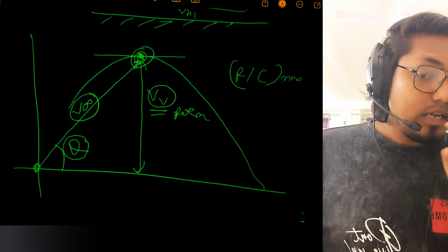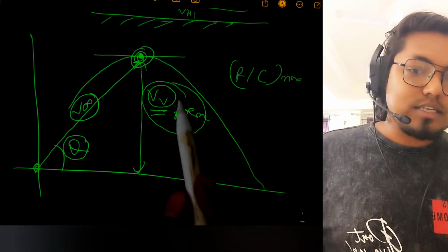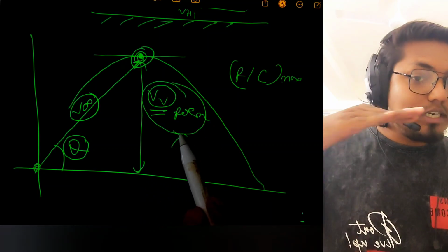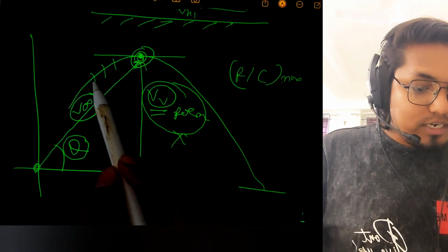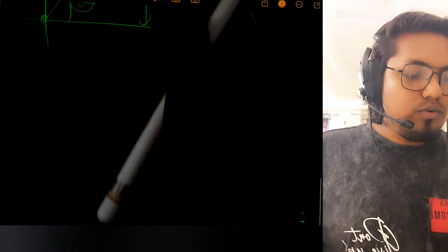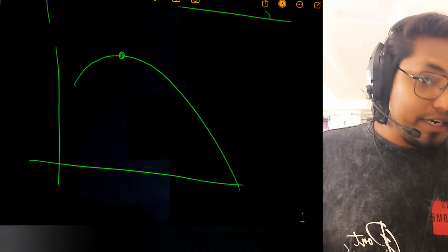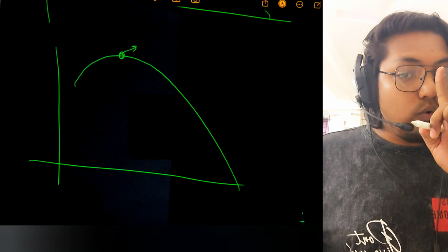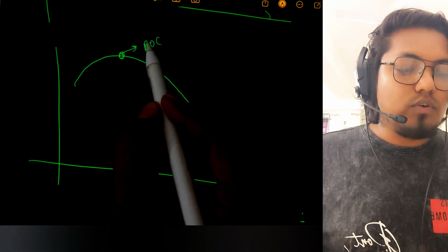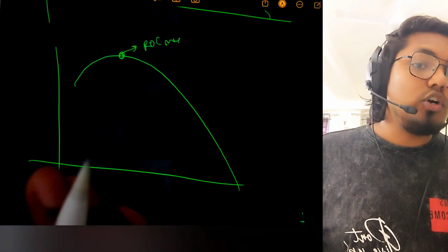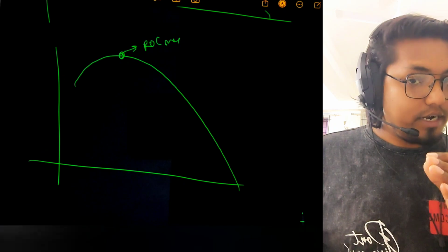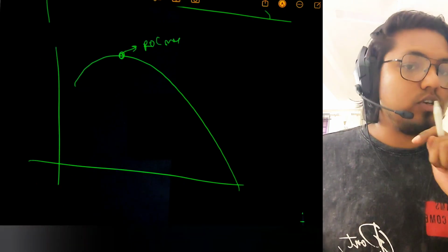Okay, now remember, rate of climb max does not mean horizontal velocity is minimum, because even these points are still remaining. So now you understood that in your climbing hodograph, at this point whatever data is there is telling you only one idea, that ROC was maximum. It does not mean anything else was minimum, or that everything was maximum. No, only ROC was maximum.